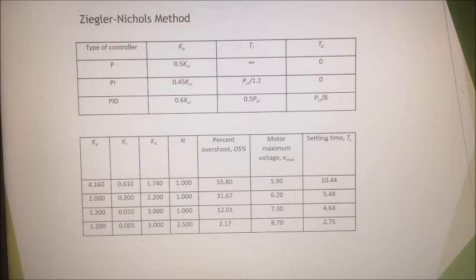Like I said before, to achieve the best design parameters, different values of control gains obtained from this method are used, and the corresponding responses are then evaluated. After that, the best values of control gains are chosen, and the response of the system and input voltage are then determined.